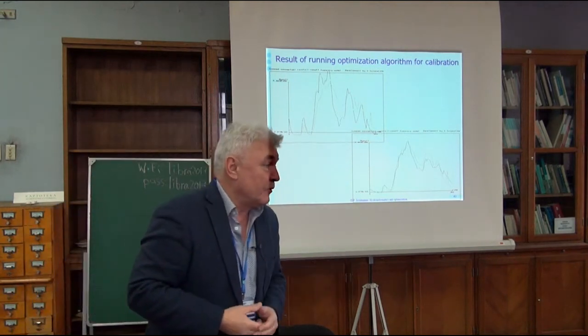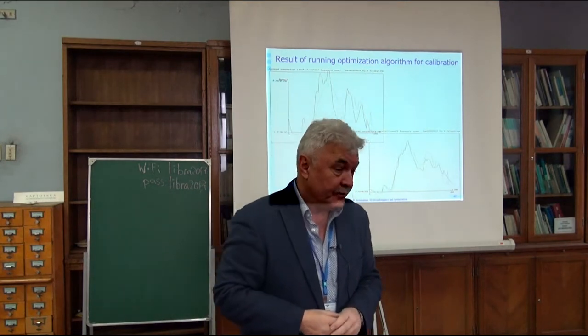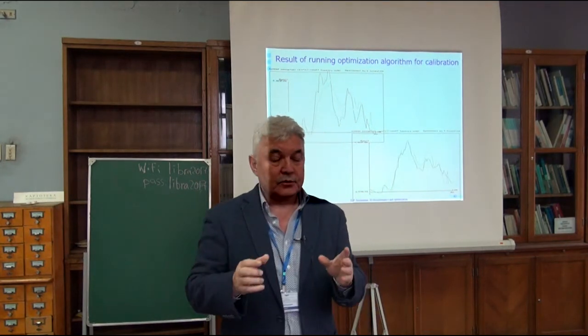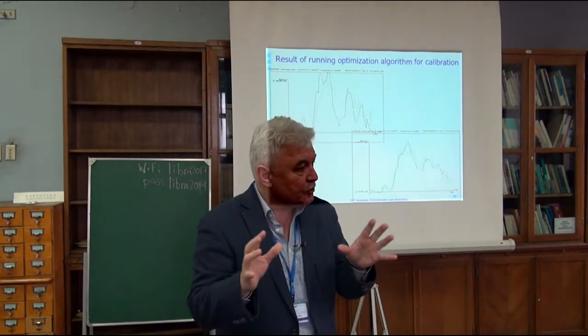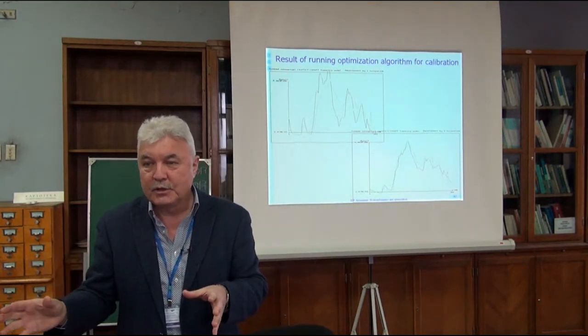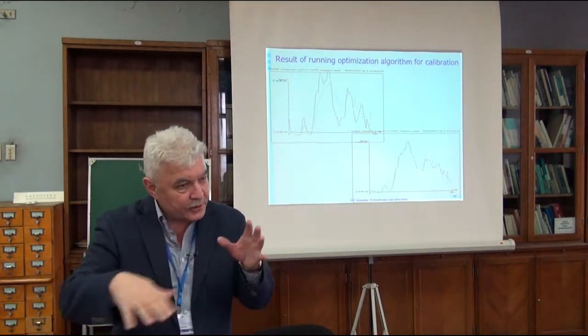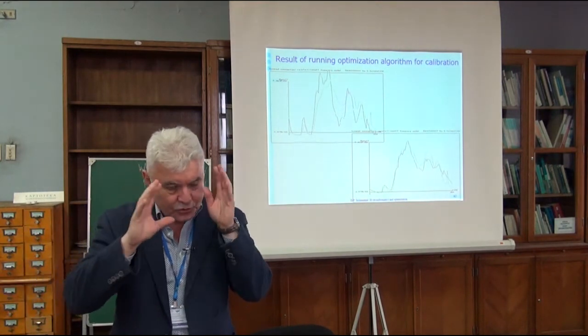There is a paper by Jean Kunsch on data and models in the Journal of Hydroinformatics 15 years ago, where he says it's not about hydrological models, it's about hydraulic models. He says, please don't calibrate river models, because actually all data is wrong, so you better measure well the cross sections and roughnesses and use your judgment.